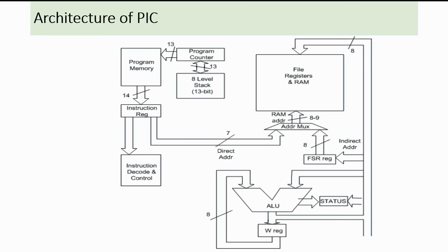Also, the arrangement of stack memory is different in PIC microcontrollers. Here, the stack is not a part of data memory or your RAM. Stack memory has its own independent space, therefore it has some finite size, and this finite size of stack memory depends upon the different PIC models that are available. Another different feature of PIC is that they do not have the stack pointer register, as is commonly available in most microcontrollers.